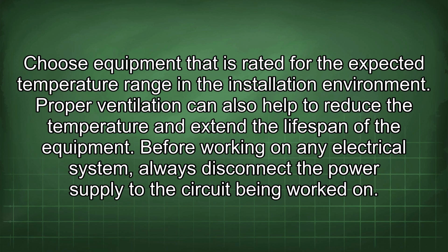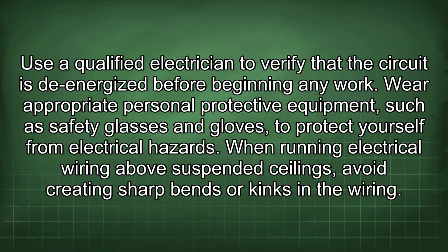Before working on any electrical system, always disconnect the power supply to the circuit being worked on. Use a qualified electrician to verify that the circuit is de-energized before beginning any work. Wear appropriate personal protective equipment, such as safety glasses and gloves, to protect yourself from electrical hazards.